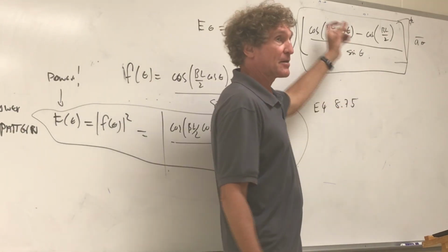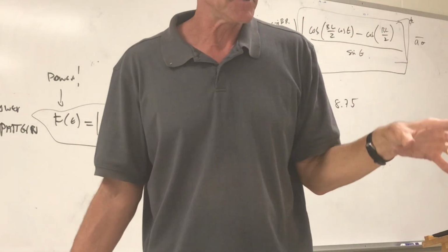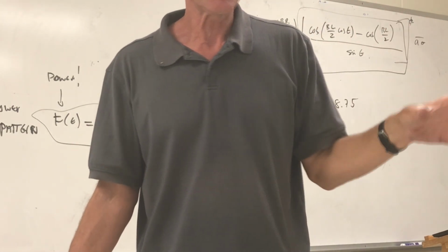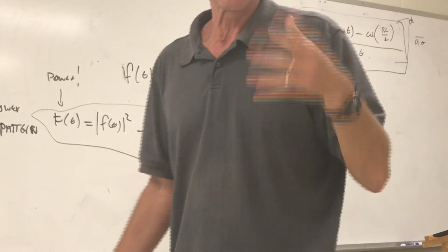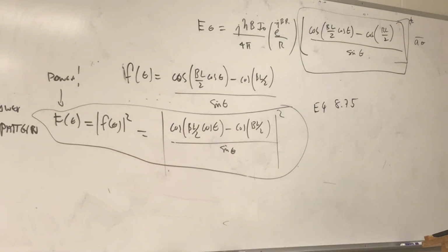But the integral is not closed form for a lot of different things, I mean, different conditions. Can you follow me in this class? I'm just telling you it's not as cut and dry as the short dipole. It's not. So that's arbitrarily long. Now we're going to go to something that's important, and that's going to be a dipole that has a specific length, and we're even going to make it a little shorter for a reason. And that's going to be the half-wave dipole.